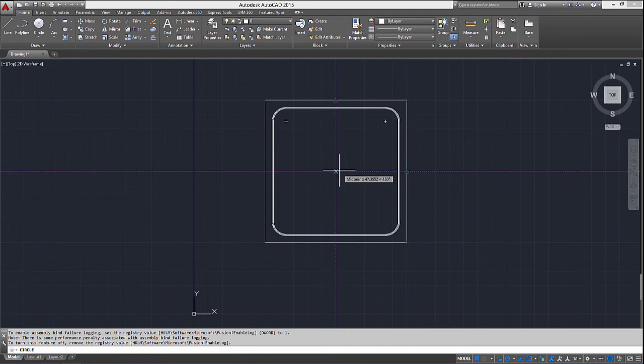Basically I want to come in and line along with that, and where it intersects with this, it doesn't matter if it's not exactly in that midpoint intersection, as long as I can see those 2 lines, there'll be a cross that maps that exactly. And then I click. That's to start my circle, which I selected many moons ago, and now we enter a radius value of 40, enter. Okay, so that's created that circle.